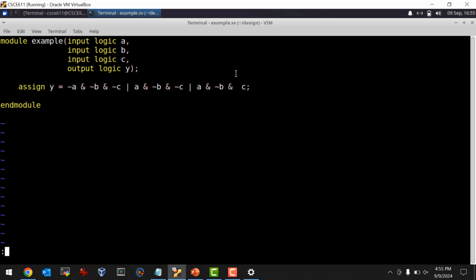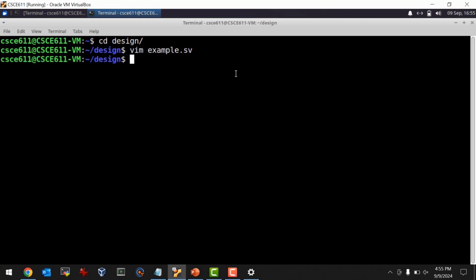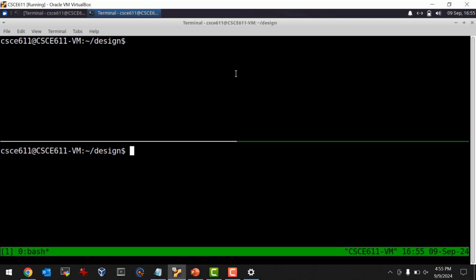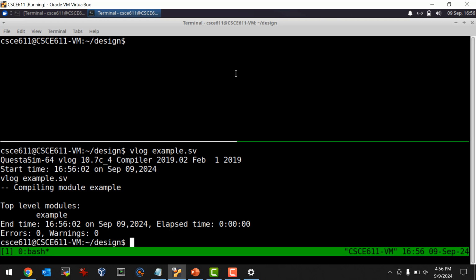All right, so I'm going to save that, and I'm going to type vlog, that's the compile command, example.sv. In order to simulate something, you have to compile it first. And it compiled.